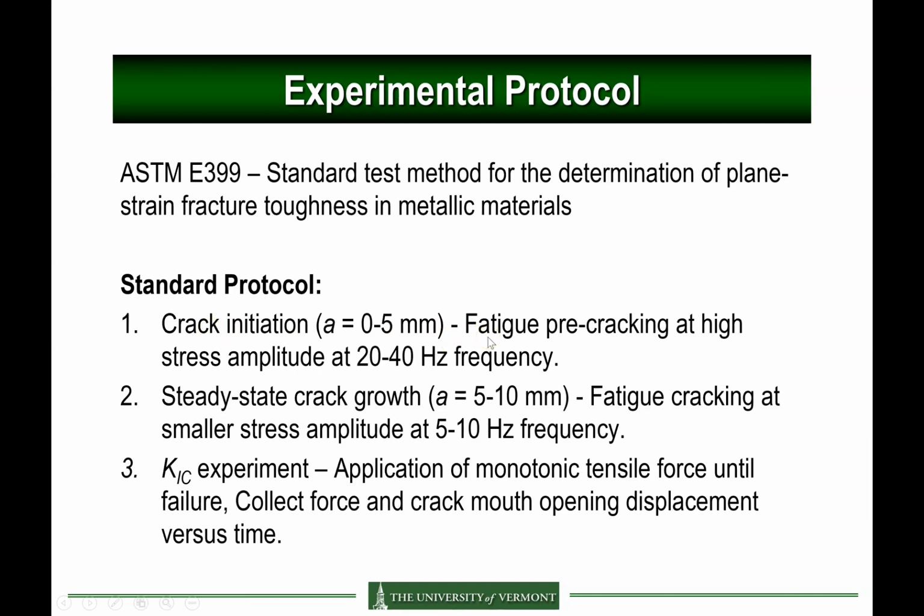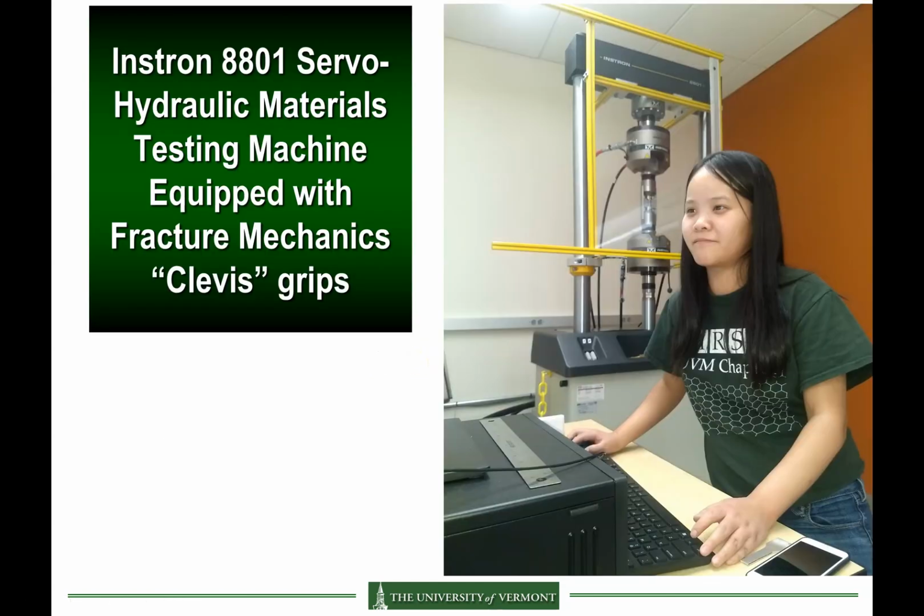This process usually requires about 50,000 fatigue cycles. So what we do is we increase the load. We have a low stress amplitude on the order of 6 kilonewtons at 20 to 40 hertz. I think we chose 20 hertz in our experiment.